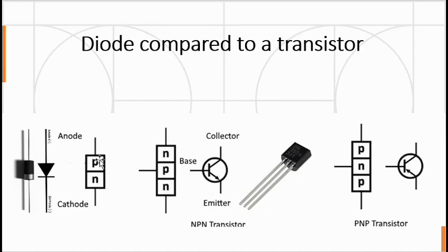Someone else said, hey, if I've got a PN junction here and I put another P-doped material on the bottom, what happens? Well, so they made a PNP, and that becomes a PNP transistor. PNP transistors are usually used in negative power supplies. So we'll be concentrating on NPN, which is like 90% of the time you'll be dealing with an NPN transistor.